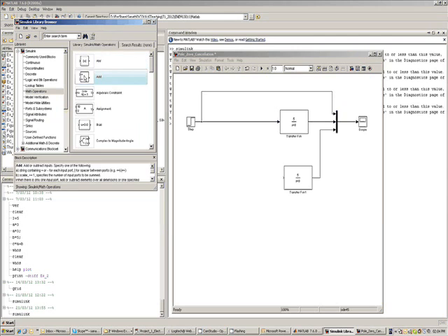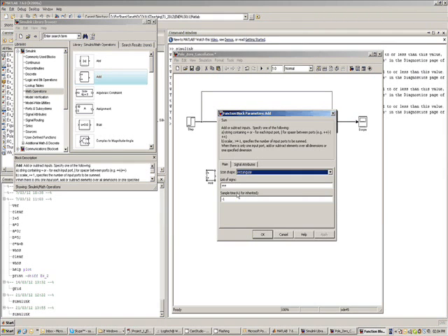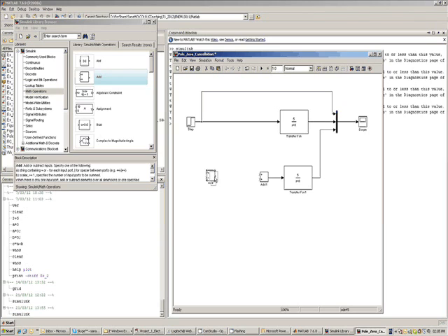And then from the math operations block, you can get a summing point. I will need two summing points. So if you right click on a certain block, drag and drop, you can get a carbon copy of the same. And then the controller will have two components, therefore I need a summing point at that point, and then I need another summing point where I compare the reference and the measurement. And then the input to the reference can be the same step.